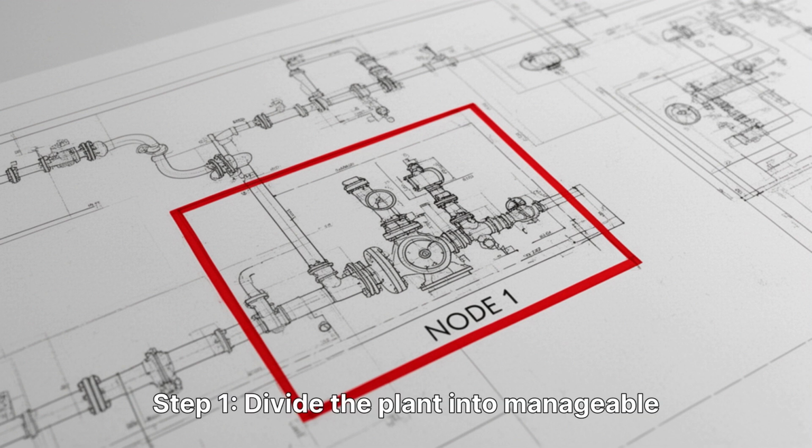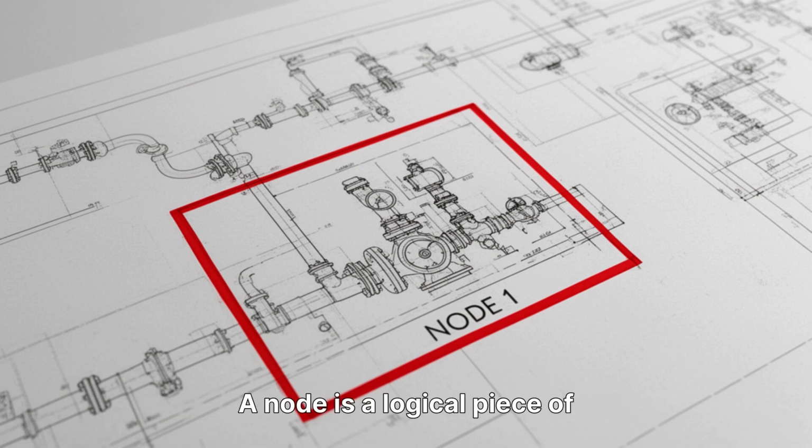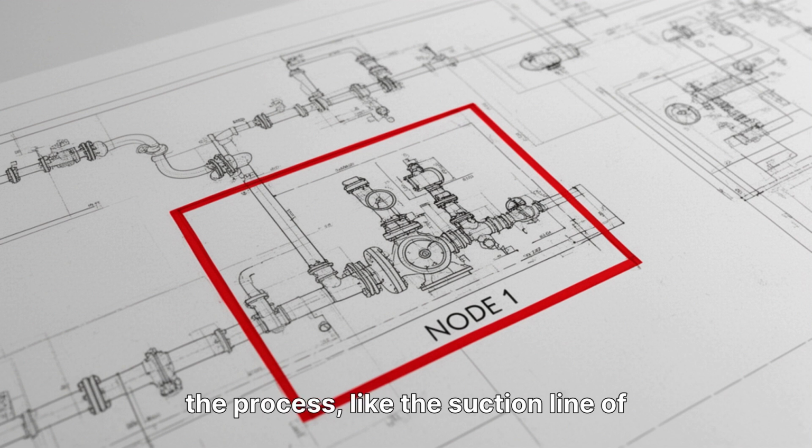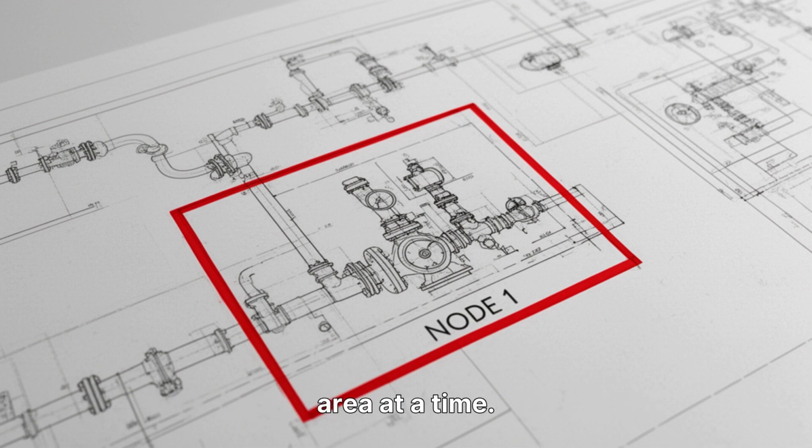Step 1. Divide the plant into manageable sections called nodes. You can't analyze a whole refinery at once. A node is a logical piece of the process, like the suction line of a pump or a single heat exchanger. This focuses the team's attention on one area at a time.